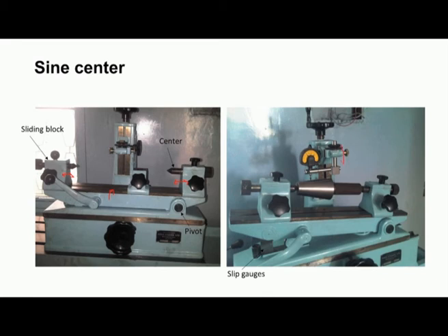head can be moved up and down. You can see the guideways here. So, this head can be moved up and down again to accommodate workpieces of different sizes. Then the dial indicator is moved horizontally till it reads 0 throughout. So, like that we should adjust the slip gauge height, and then the angle can be calculated. That will be the taper angle of the workpiece.